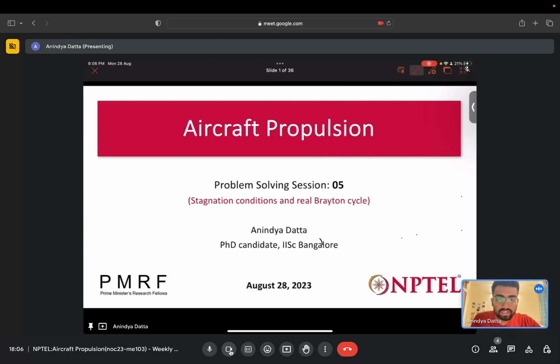And also we have looked at different Brayton cycle attachments like the reheater, heat exchanger, and intercooler, and looked into the effects of those on the net work output and the thermal efficiency when each one of them is used, and when all of them are used together.